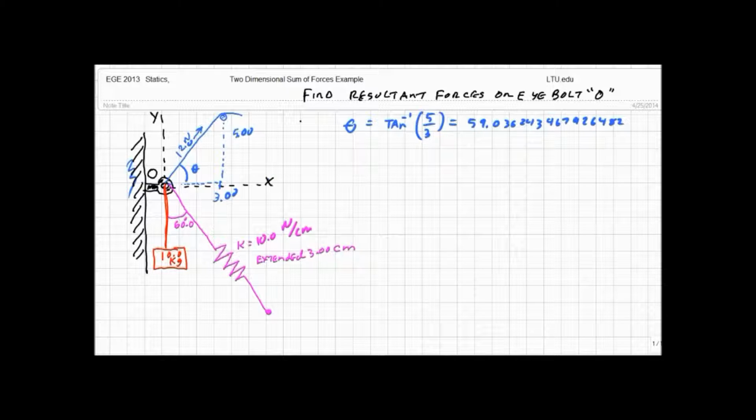It could be 5.02, it could be 4.96 meters. Whatever, it's going to be off, right? There is no such thing as an exact measurement. So when I try to do this calculation, carrying it out to about a dozen or so digits is ridiculous, right? So I've got 3 significant digits everywhere in my drawing. I'm going to work to 3 significant digits, period. Okay?